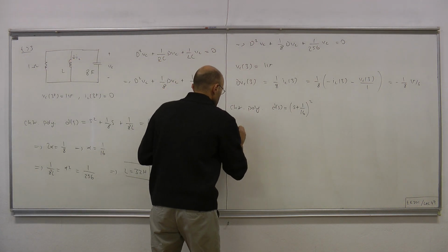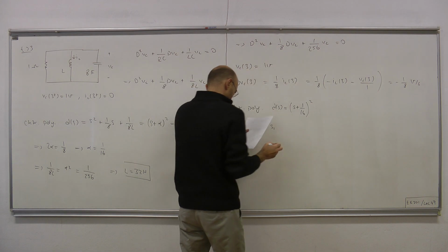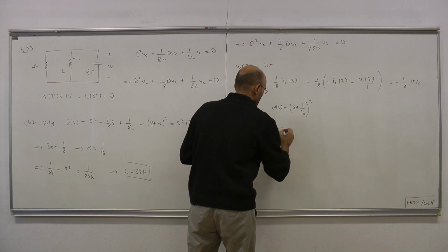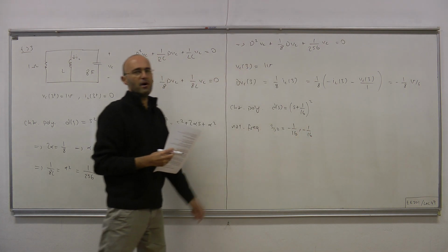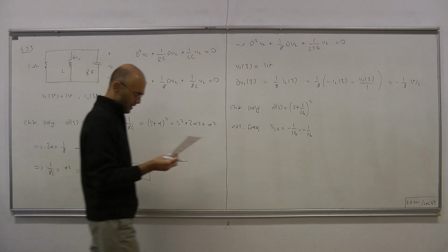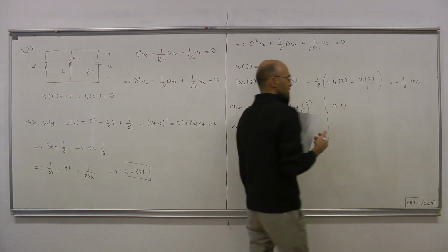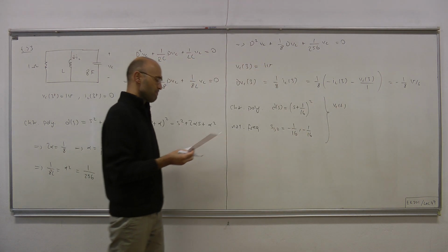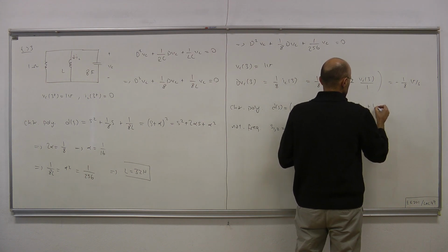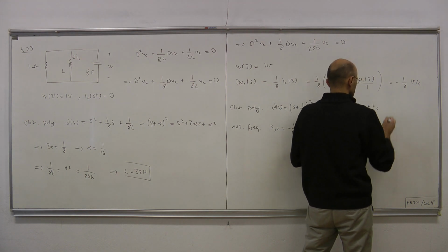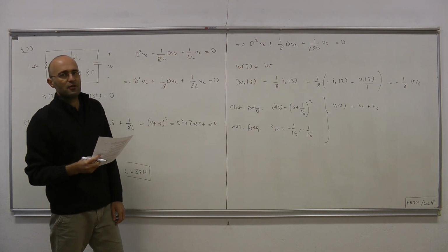And natural frequencies s1,2 are both at minus 1 over 16. Therefore, the form of Vc(t) reads as follows: K1 plus K2 t times e to the minus t over 16.